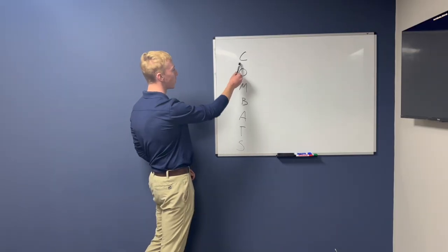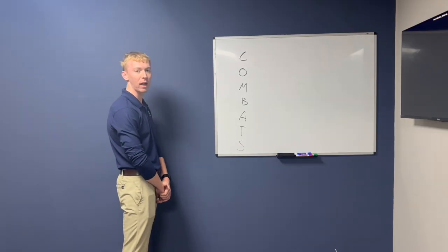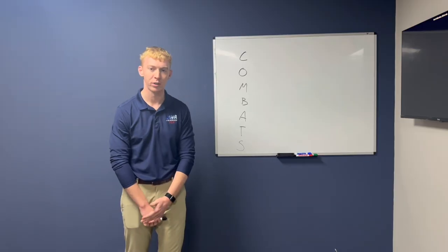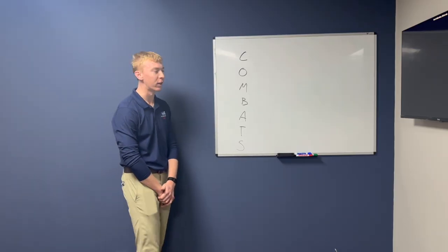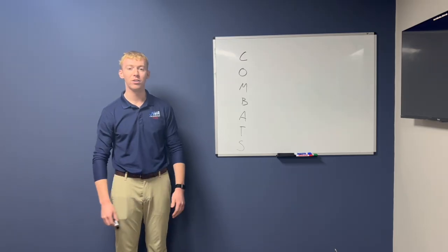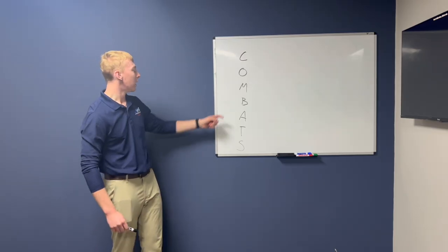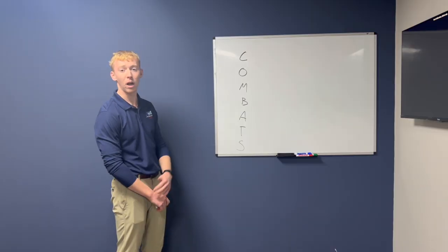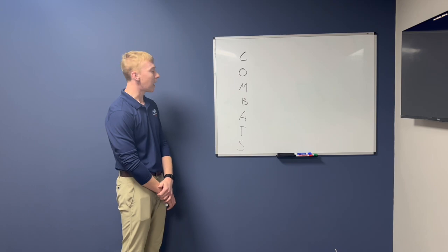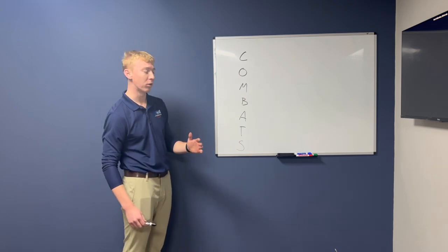The manufacturer must determine the VMC with the critical engine failed and windmilling. Our airplane does not have a critical engine. We'll talk about this in a later video. Next, they must determine the VMC speed with the operating engine at max power. The airplane must be at the most unfavorable weight. For this scenario, it'll be the lightest weight possible. And the bank angle cannot exceed 5 degrees of bank.